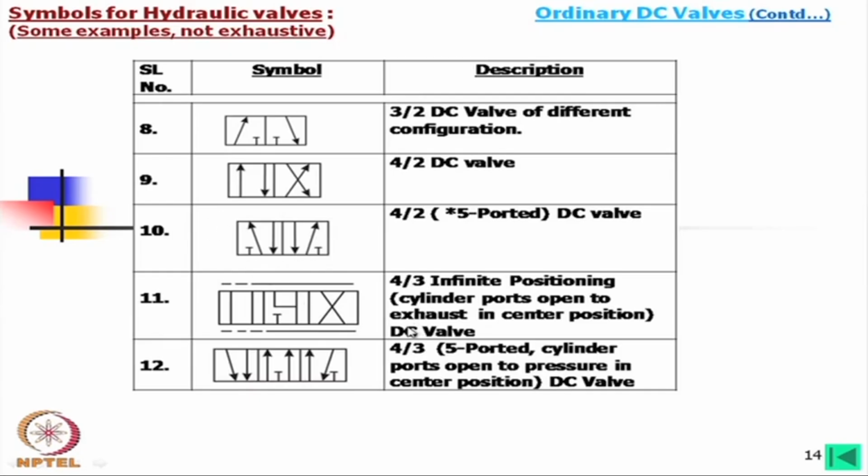Now, you see another interesting thing is that in these valves we have not used any arrow here to show any directions, but suppose if we take this block, that means basically 3 icons together, and then if we put an arrow, this will indicate that at neutral position the pressure line is closed and the other 3 ports are interconnected.